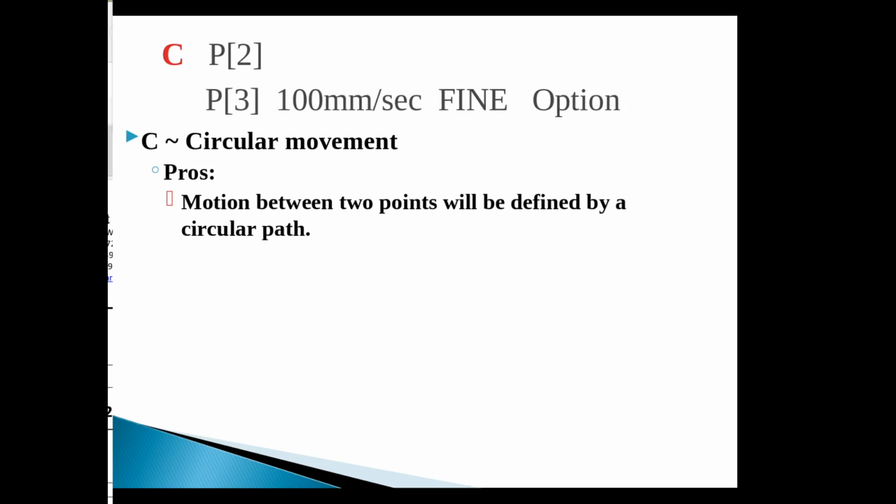All right, so these circular movements, again, we can move both linear and circular movements. We can tell it to move at a constant speed of 100 millimeters per second up to, depending on the speed of the robot, 2,000 or maybe even 4,000 millimeters per second. Okay.